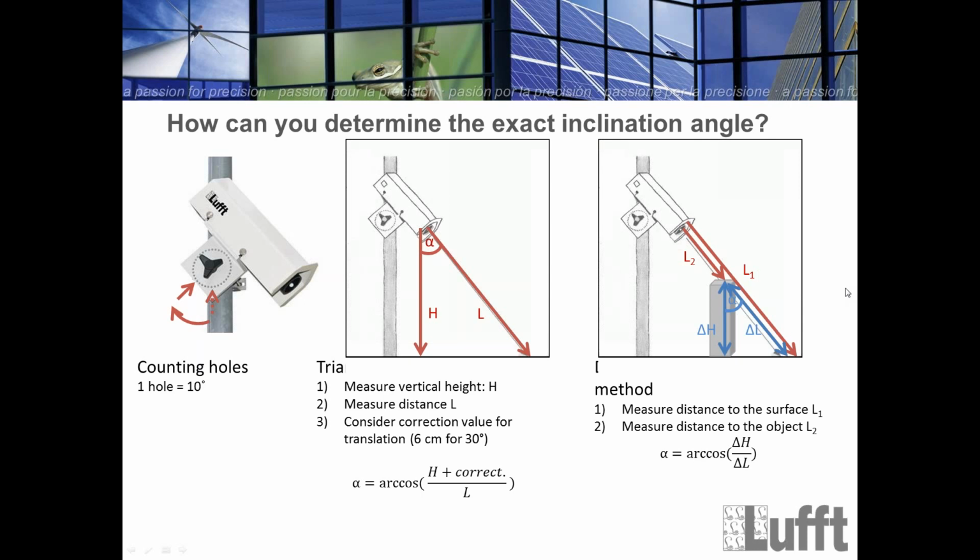Because you always have this kind of cover with you when you install such a sensor, and it has roughly 30 centimeters, you can do a very precise measurement of the height of this cover plate before you start with the installation. In reality, it's 30.2 centimeters, something like this. Then you can use method number 3 to do such a measurement.